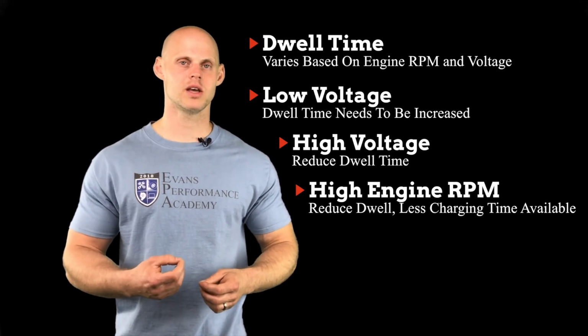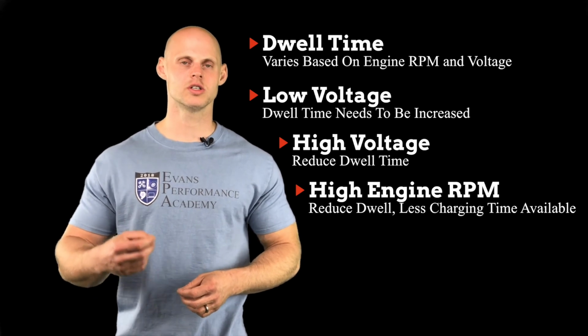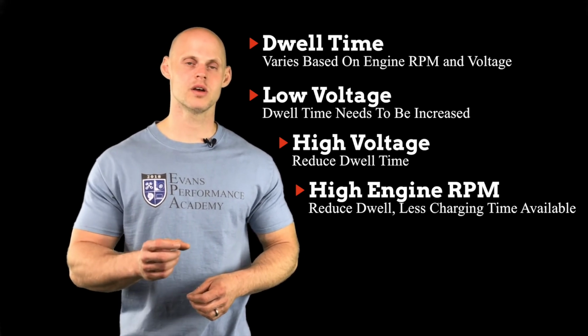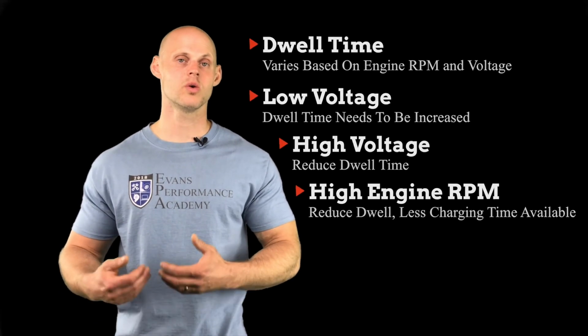And it's going to be the same case with our coil dwell. We're going to have less time to charge and discharge our coils. So we're going to use less coil dwell as our engine RPM increases, so that we don't overheat our coil.